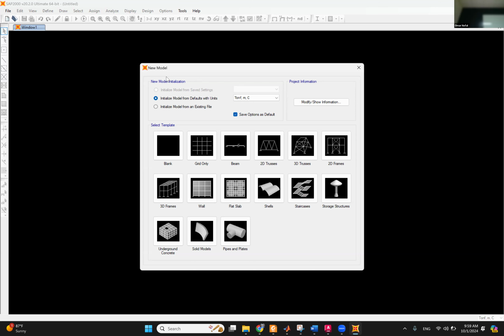It asks you for many parameters, like the spacing between the panels or the height of the truss. Or you can build a grid system that helps you draw the truss very quickly. Or you can already have the truss drawn in AutoCAD and import it right away. So I start with a blank page and import the file from AutoCAD to SAP 2000.